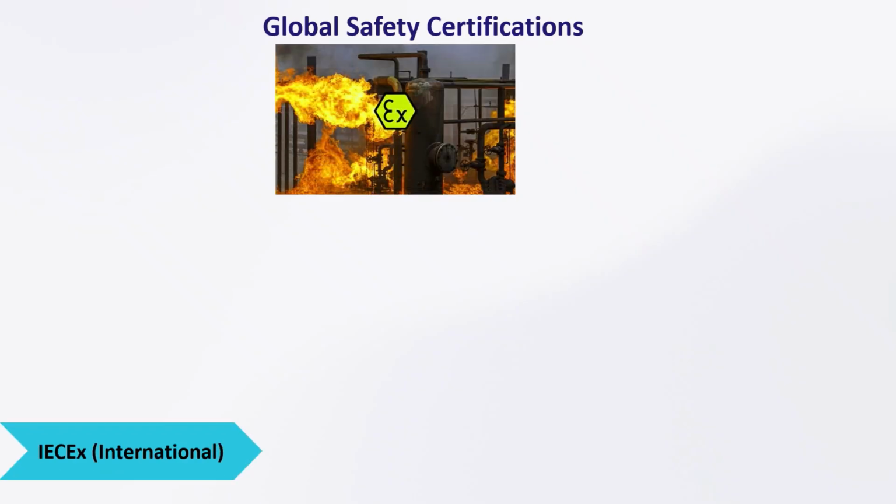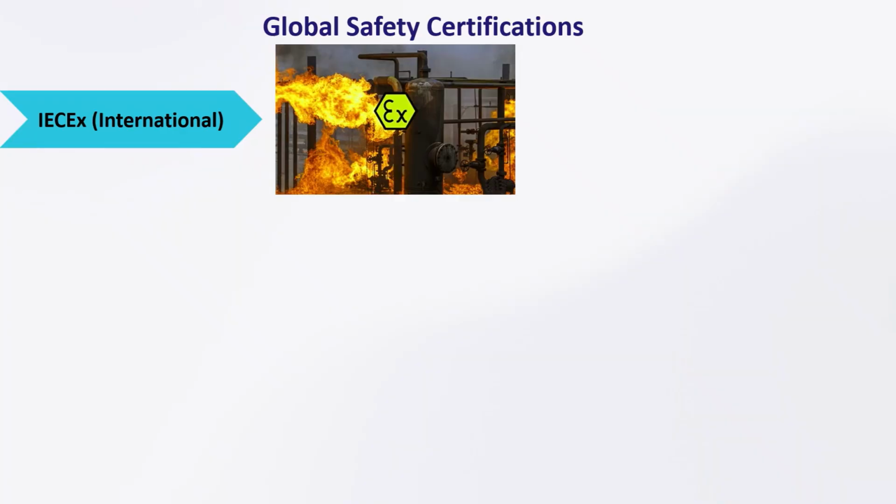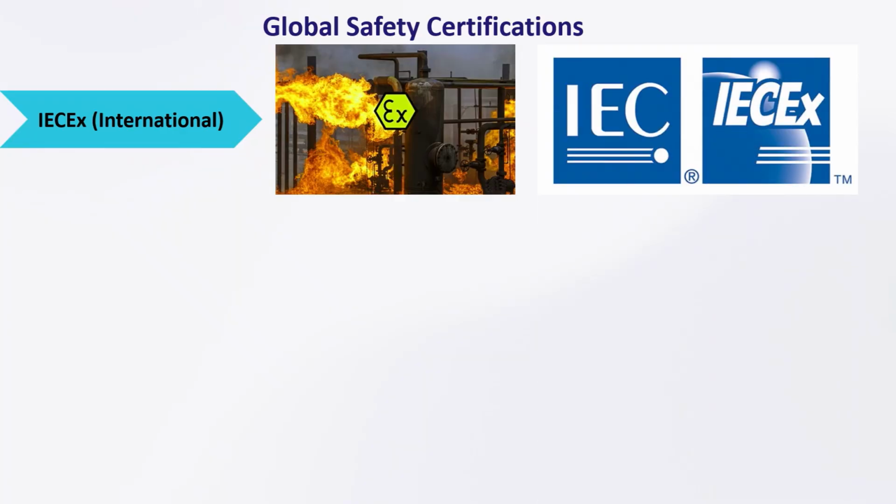A. ATEX stands for Atmosphères Explosibles, governed by the EU Directive 2014/34. It classifies equipment into zones and categories. B. IECEx certification. IECEx is similar to ATEX, but it is globally accepted according to the IEC 60079 standards. A typical marking looks like Ex ia IIC T6.